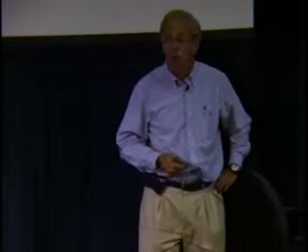And so, what I will posit is, as we move forward and everybody starts building chips with hundreds of cores on them, what is going to matter is finding enough parallelism to keep hundreds of cores busy, but even more importantly, managing the transfer of data up and down this memory hierarchy so that hundreds of cores can share one very skinny pipe off the chip. And the right way to do that is to expose this hierarchy as a tree structure of memories, and then use bulk operations to choreograph the data up and down the tree. So with that, I'd be happy to take any questions you have.